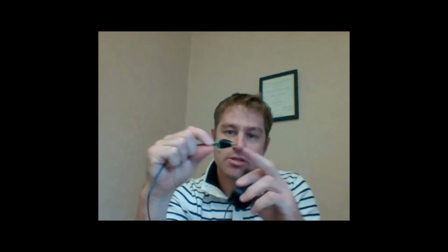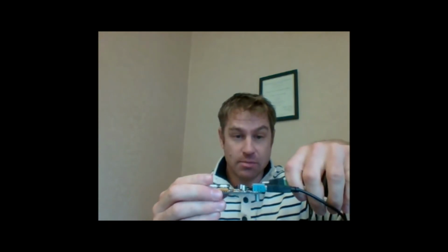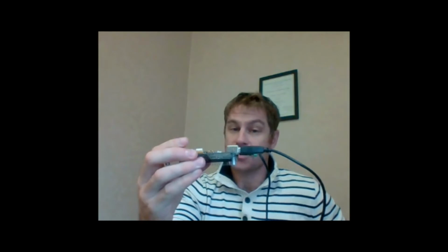So this is, oh yeah, that's right. Sorry, I read too quickly. This is a 7.5 volt, 1 amp maximum rating battery supply. So you connect it into your board, and it will supply you with DC power. Now, to connect this battery to your embedded processor kit, we sell additional connectors so that you can actually plug it into the embedded processor. So I plug it over here. This is my DC supply, and I plug it into the wall. In my case, it's my power bar.